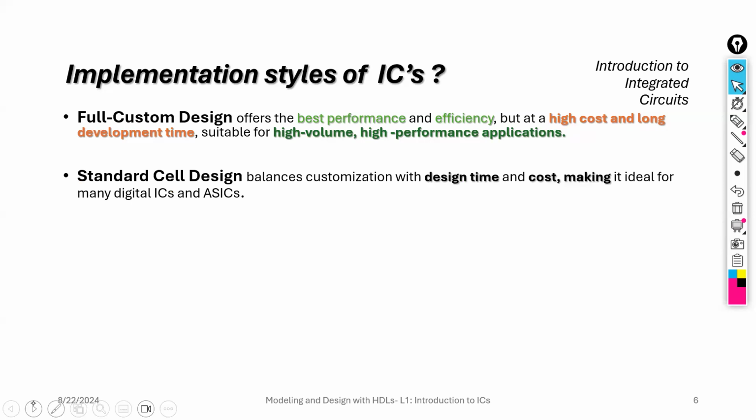Next, for standard cell designs, we get a balance of customization with design time, cost and marketing. It suits many digital ICs and ASICs. People will go for the standard cell approach because design time is a little less, and the time to market and costing are also less compared to full custom designs.